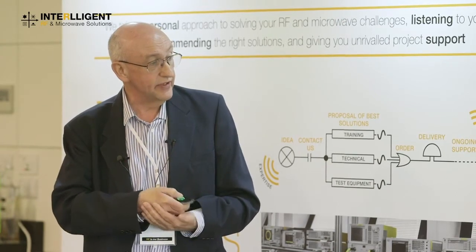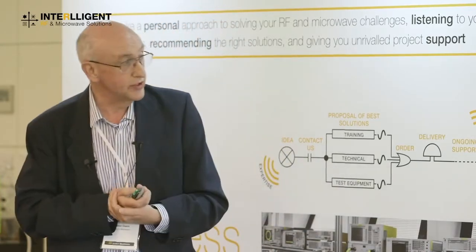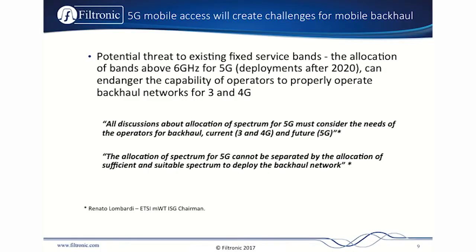And there's a statement here from the president of the ETSI mmWave wireless transmission group, making the point that any discussion about spectrum for 5G must consider the operator's need for backhaul, not just for 5G in the future, but for the existing 3 and 4G. So if we start reallocating bands for access, it's going to cause problems with the existing fixed infrastructure.